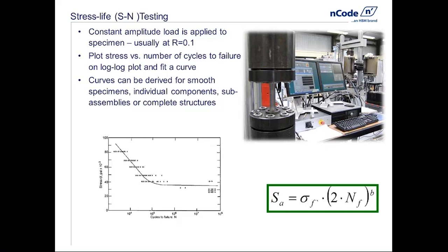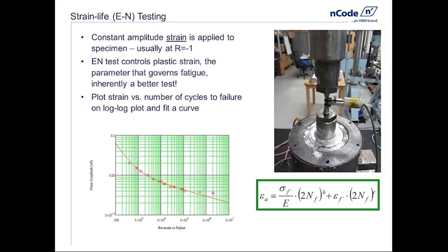You can do the same in actual terms, and the result of that produces the little plot you see bottom left there. You can see from the X's on there that there are a whole series of tests at identical stresses, and that gives you the lie on the way fatigue behaves. You don't get a single life with a single stress, you get a range of lives. There's plenty of scatter, and the longer the life, the more the scatter is. That's one way of testing it.